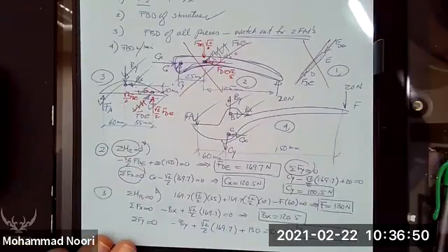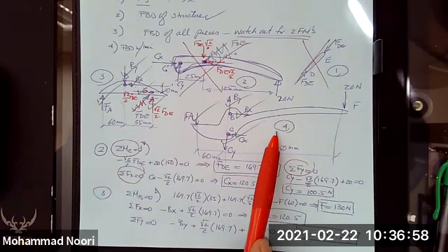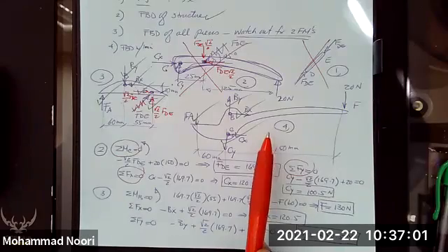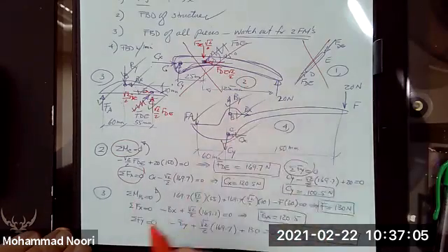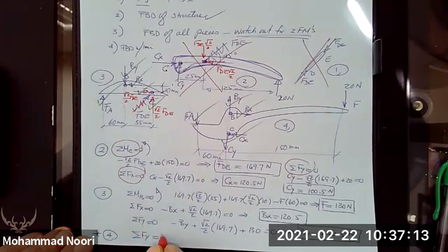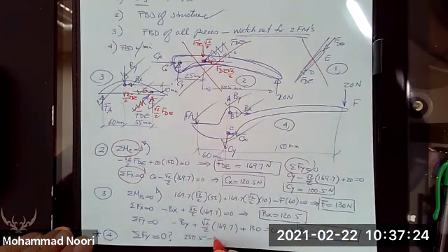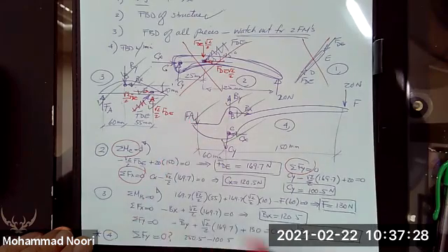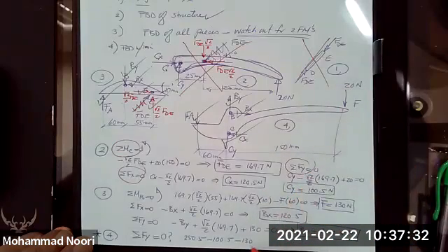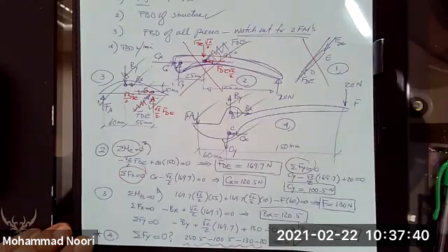So what happened now? As we know, we have ended up with one free body diagram that we have not used, which is free body diagram number 4. Use that to verify your answers. I'm not going to do it for all of them. Let's just use number 4 to see if summation of forces along y is 0 or not. So at By upward 250.5, Cy downward negative 100.5, F downward 130, and then 20 downward, right? These add up to be 0. So that means the answers that I found were correct. And this confirms that.